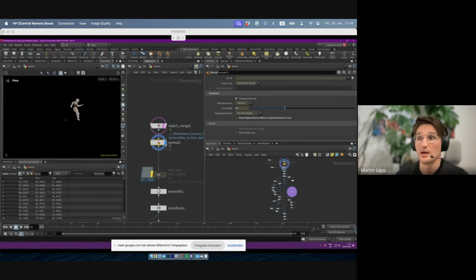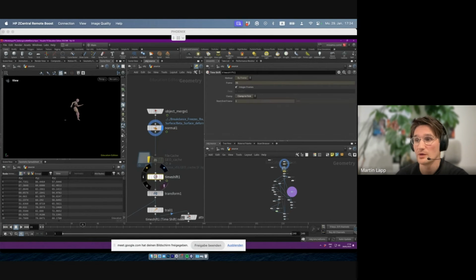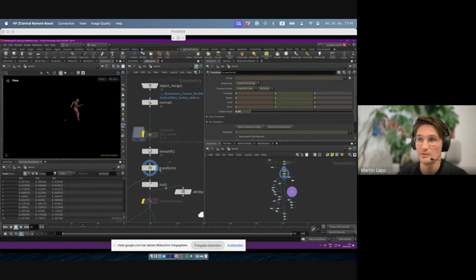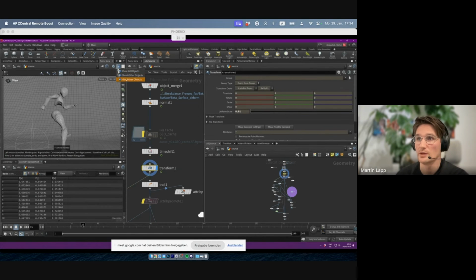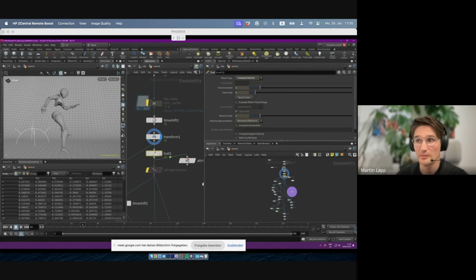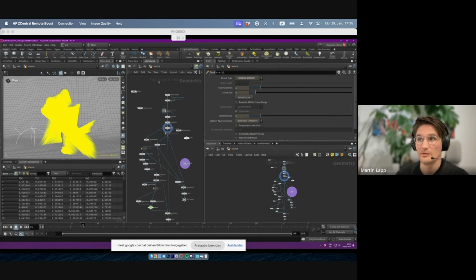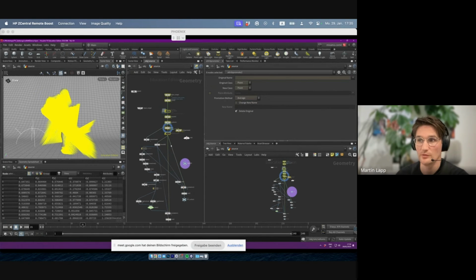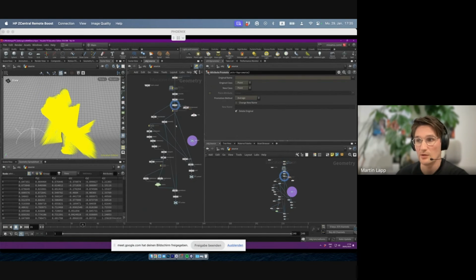It just takes it automatically. Again, I'm giving him normals. I'm time shifting him to make sure that I only have integer frames, and I'm clamping him to the first. I'm scaling him down so that from my camera it kind of makes sense. I'm giving him velocities by trailing him. Like so. So this is exactly the same as what you've seen before, right? And now comes the change.